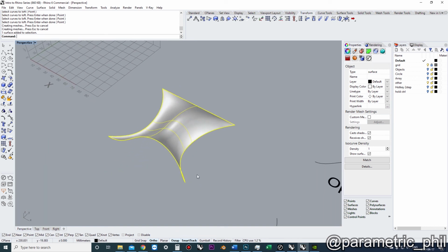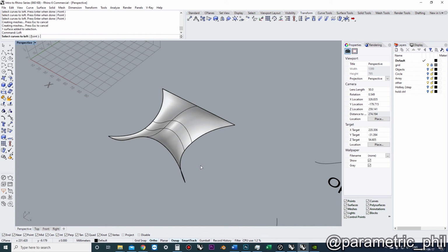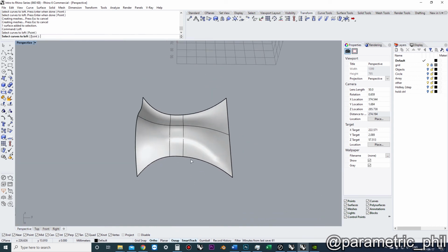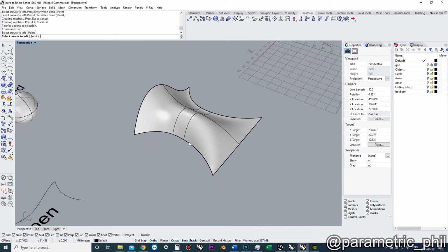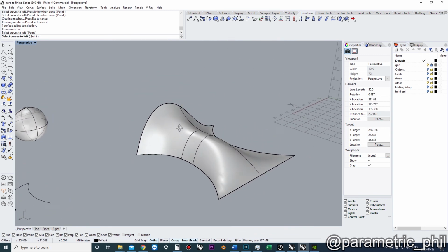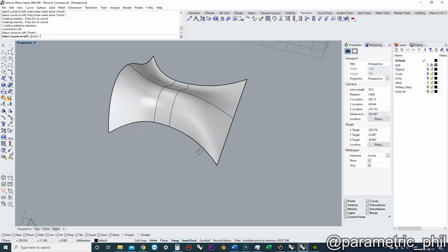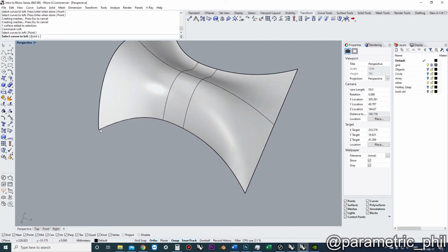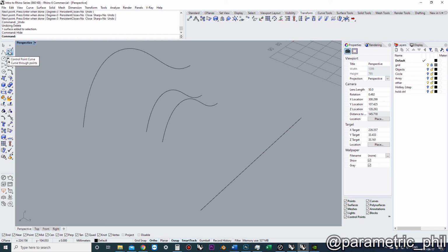And the other main one that you're going to be using if you're doing these types of surfaces is sweep. So let's say that we have a surface like something like this, but we want to have more control of what this edge shape looks like. So I'm going to use an interpolate points curve here because I want this line to intersect the points that I'm drawing perfectly.